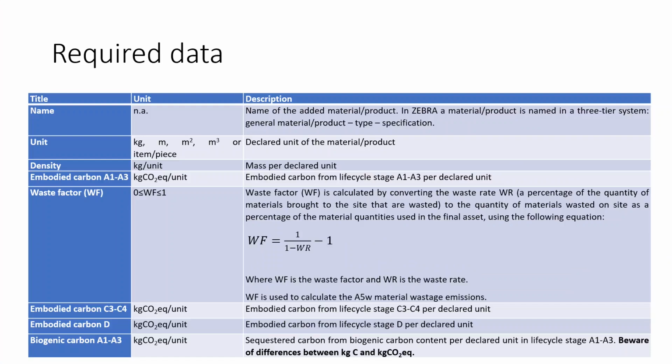In the latest standard, biogenic carbon should be declared separately from the other embodied carbon from fossil fuels and from land use. But in some older EPDs, you may not find this value. There's an equation provided in the accompanying essay to help you calculate this when no value is presented in the EPD.